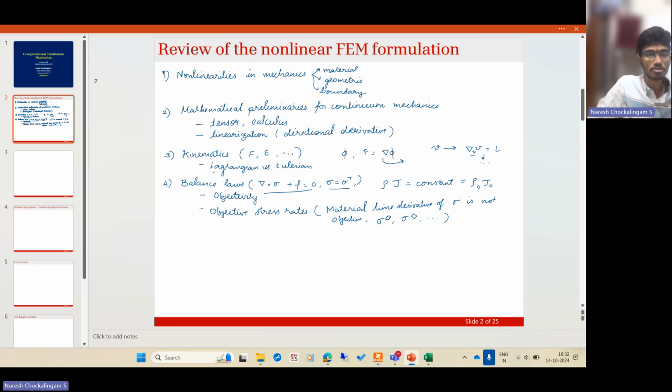Now the next part is to put these two together. We have kinetic quantities which deal with the forces, stresses, and their rates. We have kinematic quantities which deal with the deformation, its gradient, and the time rate of the deformation. The next task is to relate these two, and that is basically constitutivity. But in constitutivity, there was a requirement of work conjugacy for the quantities that can be related.